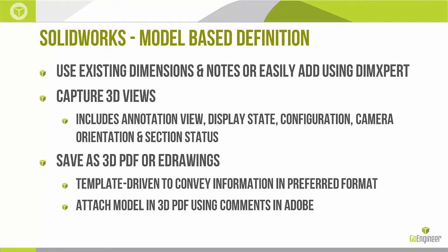So SOLIDWORKS MBD gives us the ability to use existing dimensions, all the annotations, everything that we've got in that model to capture as 3D PMI. We're able to create 3D views, and 3D views are much more powerful than just, say, a named view, because not only are we grabbing the camera angle, but we're also grabbing the annotation view, display states, configurations, section status, as well as that camera orientation. And then we have the ability to save these off as dynamic 3D PDF documents or e-drawings.